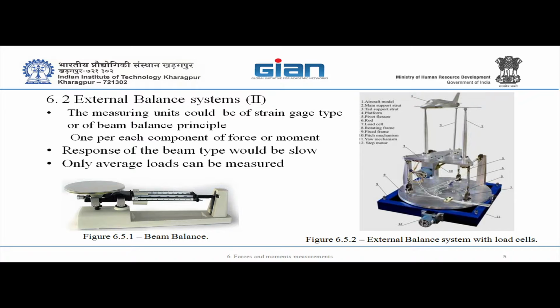They can't do dynamic measurements when it's a beam balance, because it takes time to balance. Do you have this in your clinic, in your hospital? Sometimes you have to measure your weight. There is a mechanical one that you stand on, and you have to balance it with the weight. You remember? This is the same principle here. There is a stepping motor which moves this weight until it equals the load. So it takes time.